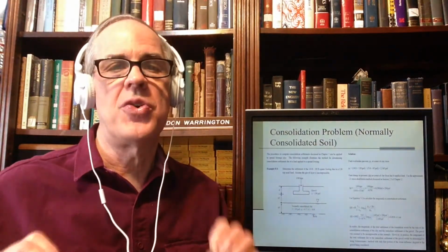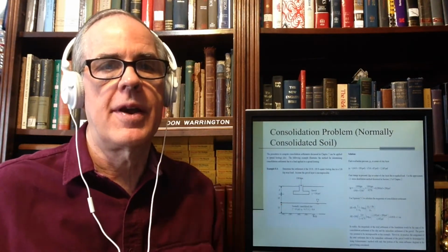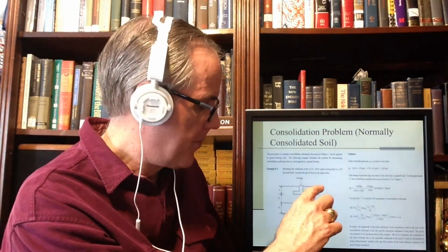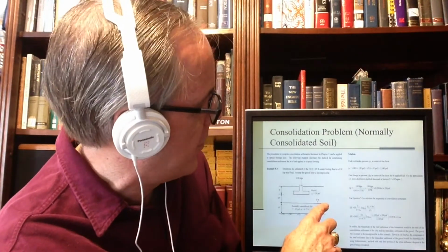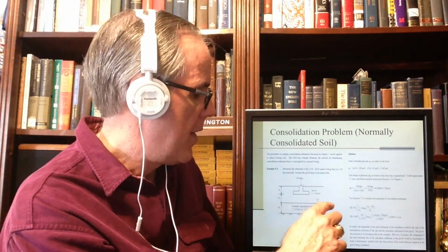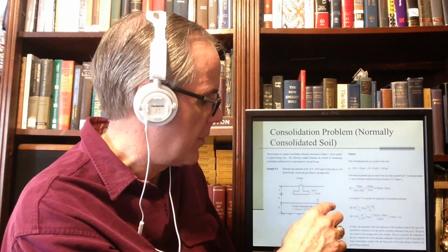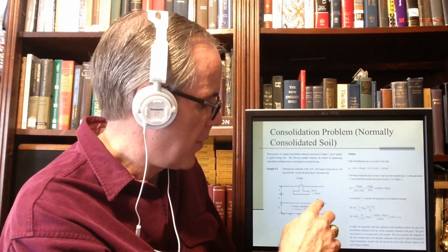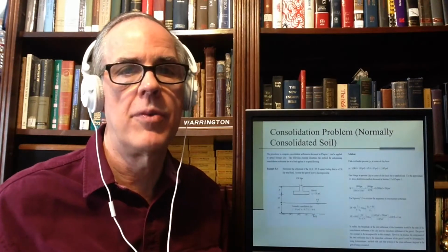The other way to do it, the formal way, if you want to, is to do the whole P0 diagram thing and start with 0, and then the total stress here will be 14 times 130, and there's no pore water, so minus U is 0, and you'll get effective stress here. Then you go another 10 feet, where it is 5 feet. Now they use the submerged unit weight. That's what you're given. If you're given the submerged unit weight, you don't worry about the water. We talked about that earlier.